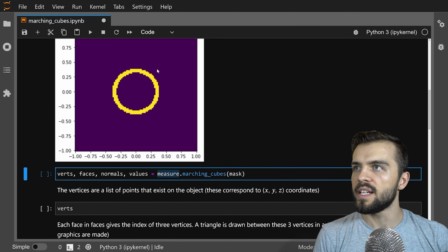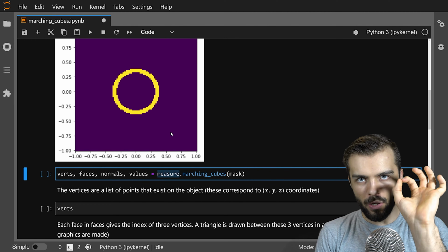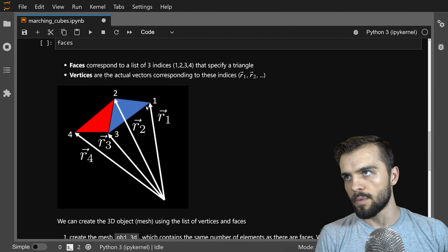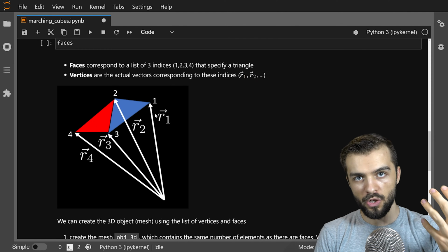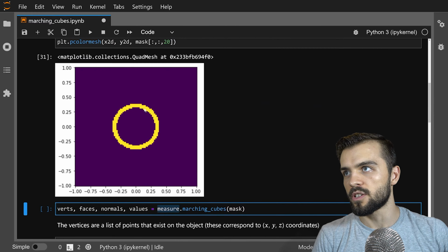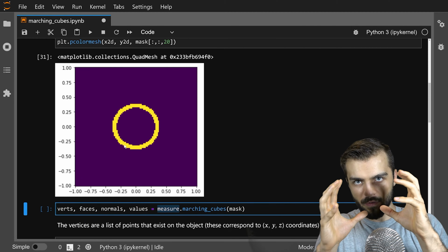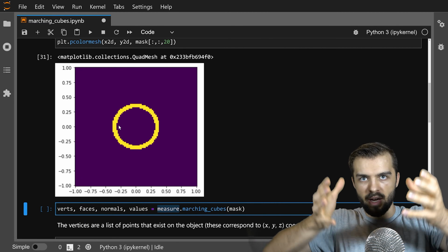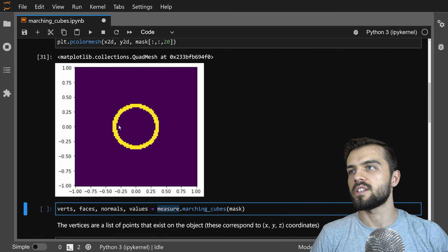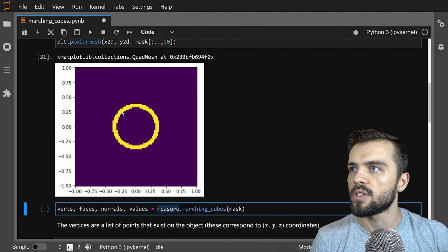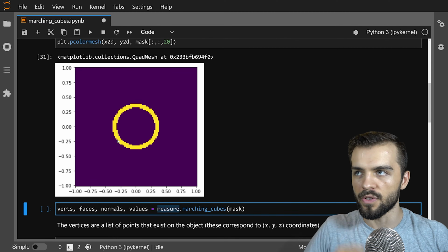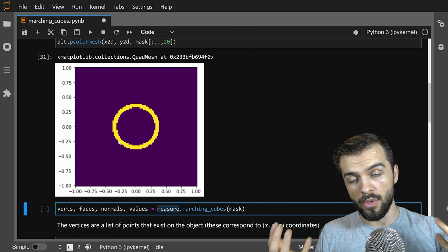All you do is feed in this mask here, and it will find all the given points with the triangles on the surface. By the surface, you actually mean the inside surface and also the outside surface. It's just going to take a connected volume. So you can think of this as going up, like a finite wall thickness. It will find all these points on the surface and all the points on the outer surface, and it will construct those into a 3D volume.